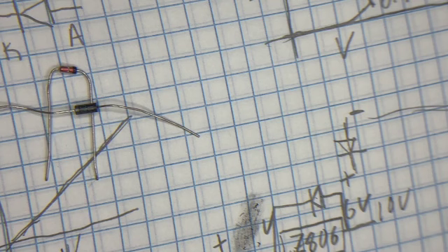There are Schottky diodes, which have a much lower forward voltage than these. Still really great at reverse voltage protection. In fact, Schottky diodes are often used to rip people off when they're trying to buy germanium diodes, because germanium diodes and Schottky diodes have really similar forward voltages.